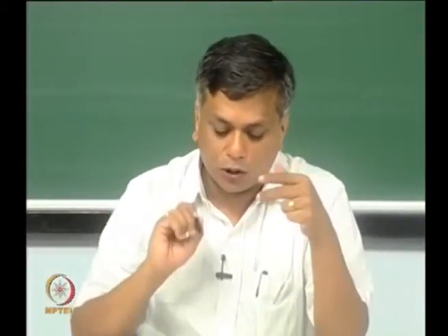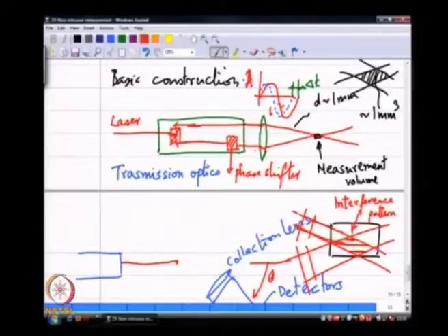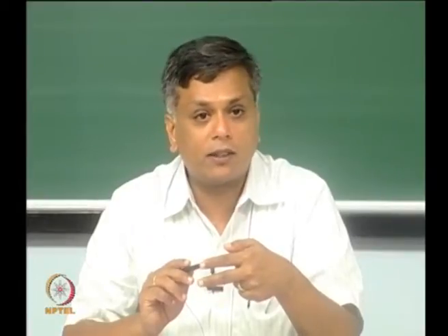Ideally my dark band should be pitch black if the intensities of the 2 beams are exactly equal. I will get the dark band to be nearly perfectly dark and the bright band to be bright. This is important because this contrast is what I am going to use for particle velocimetry and sizing.